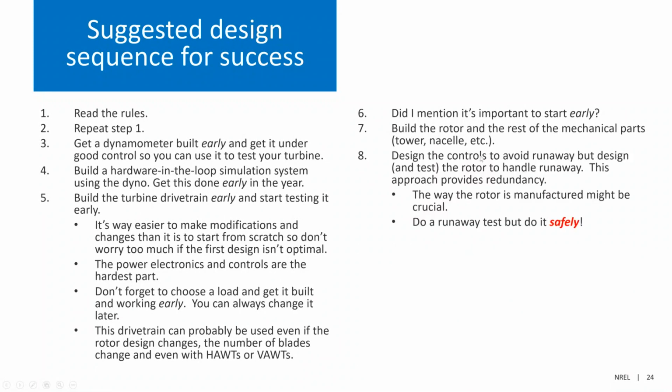Make sure you design the controls to avoid wind turbine runaway. Remember, we talked about how disastrous a runaway can be. But also design and test your rotor to handle runaway. That's one of the milestones that you have to do. So this is your redundancy. Design it to avoid runaway and to handle runaway.